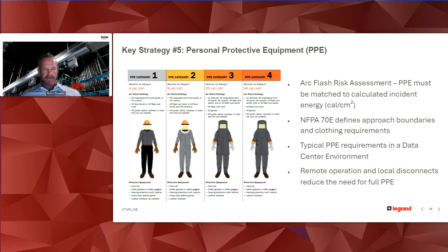Mimic panels, same way. It's basically a set of control handles that are mounted on the sidewall. It's out of the arc flash zone. And again, it's all designed for technicians to safely operate the equipment and be out of the hazard area there. So now let me do the next slide here.